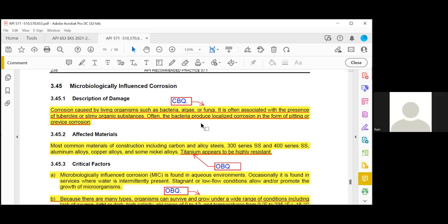For example, you mentioned caustic corrosion usually occurs at boilers and steam generators. My question is, microbiological corrosion occurs usually in which equipment? Storage tank, product side bottom. And the heat exchanger. So that's what I want to note, because I was asked in an interview but I couldn't answer it. So it is a storage tank related damage mechanism. Most of these 11 damage mechanisms are storage tank related. Some are not storage tank related, but they are included in our exam.